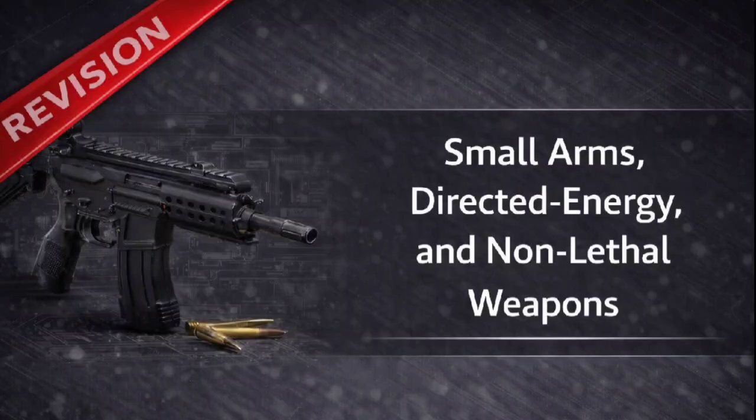All right, let's move up the scale to the self-loading rifle, or SLR. Mechanically, it operates on the same fire control principle as the self-loading pistol, right? Precisely the same. The SLR fires only one shot per trigger pull. The big difference is that it utilizes the much, much greater energy from the burning propellant of a rifle cartridge to automatically complete that entire reloading sequence. So it extracts, cocks the firing mechanism, loads a fresh round. All of it. It completely removes the need for the soldier to manually cycle the bolt after every single shot.